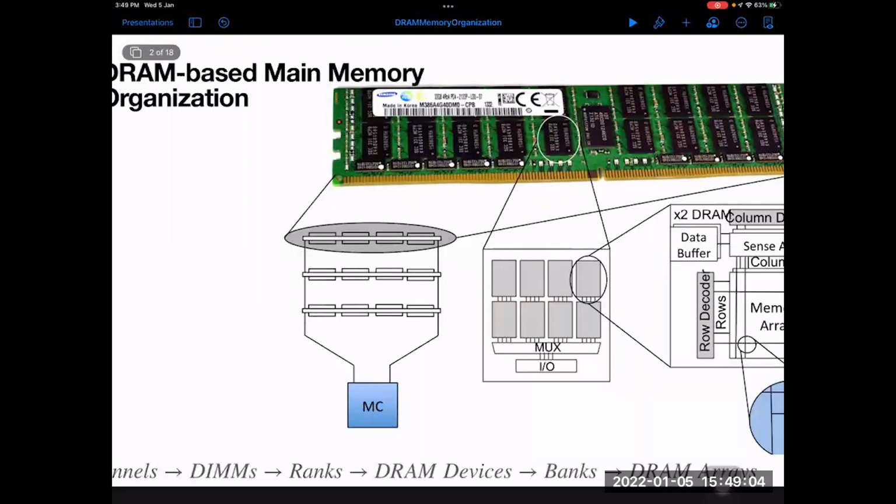Because in the DRAM, to optimize the DRAM design, some cells are considered anti-cells and some cells are considered true cells. In a true cell, logic 1 is nothing but the charge in the capacitor being above the threshold. In an anti-cell, the charge in the capacitor should be below the threshold to be represented as logic 1. That is the reason why, in a DIMM, some cells will be true cells and some will be anti-cells. Because of the repeated access of one particular row, this has an influence on the adjacent row, the adjacent row leaks its charge, and because of that, the bits are going to be flipped.